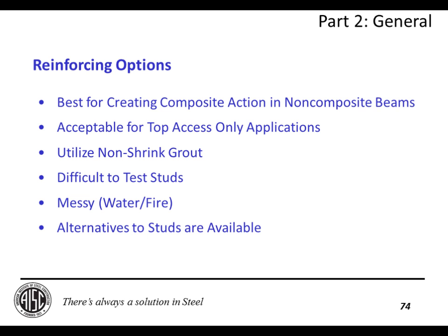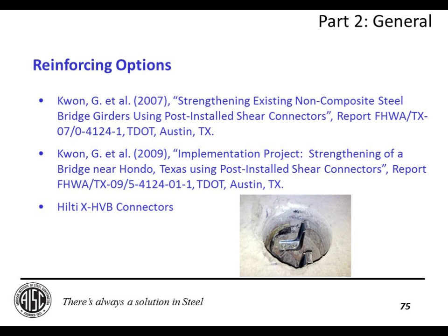So there's a couple of options other than using a traditional shear stud. A lot of these options were tested for bridge retrofit work for the Texas DOT. I listed two references here where they tested all sorts of things. They looked at through bolts, at screw anchors, at adhesive anchors, basically any option you can think of, they retrofitted a beam with it. So those are some good resources for that.